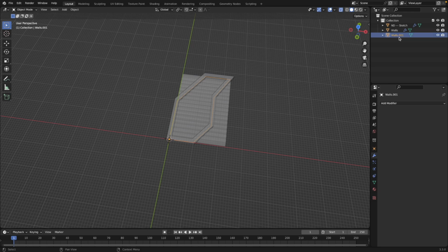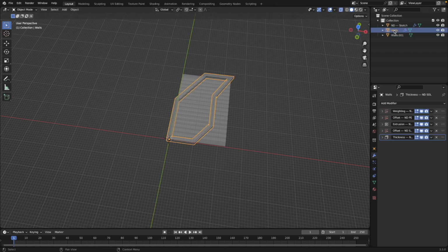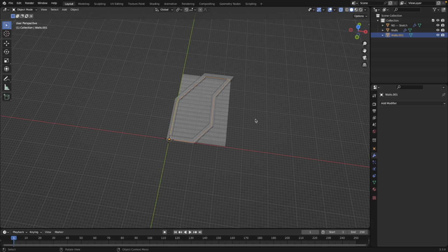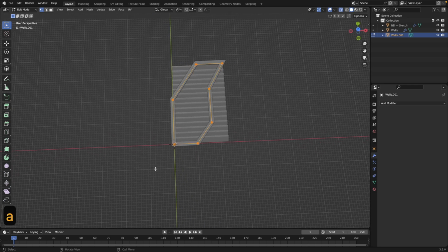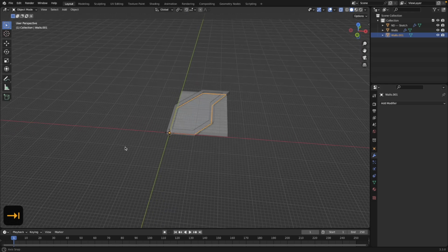So basically now I've got this copy, but it's just the outline. It doesn't have any of the three-dimensional modifiers that we've added to the actual frame itself. So the frame is here, our copy is here, it's just that shape. Now we can tab into edit mode for that shape, and we want to select all of the vertices and hit the F key, which allows us to make a face to fill that in. So now instead of just being the outline, it's actually a solid representation of that shape.